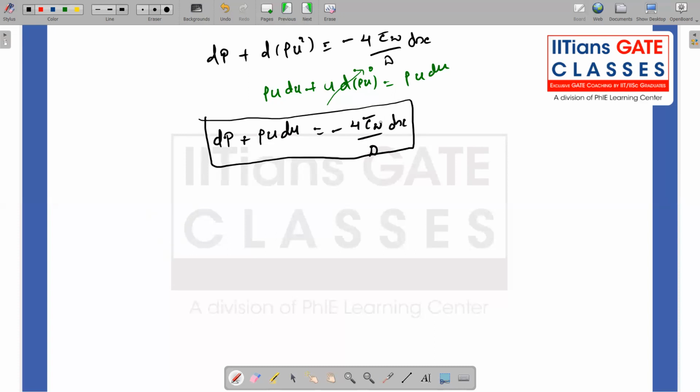Now this calculation of tau w as a function of x is not that easy a job. So all we can use is empirical ideas, because tau w is proportional to the velocity squared. That's the drag. You have used it in your aerodynamics and all. So the drag can be written as half rho u square times Cd. Here I am using the frictional coefficient f.